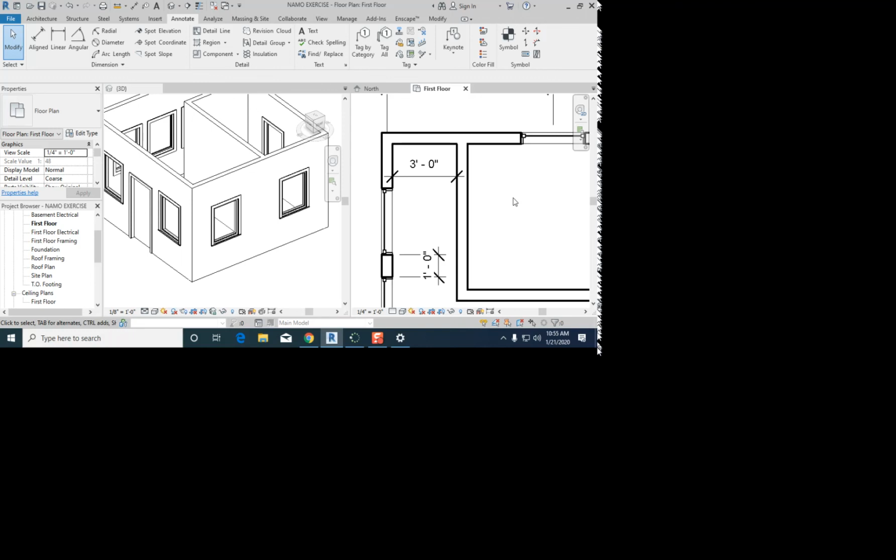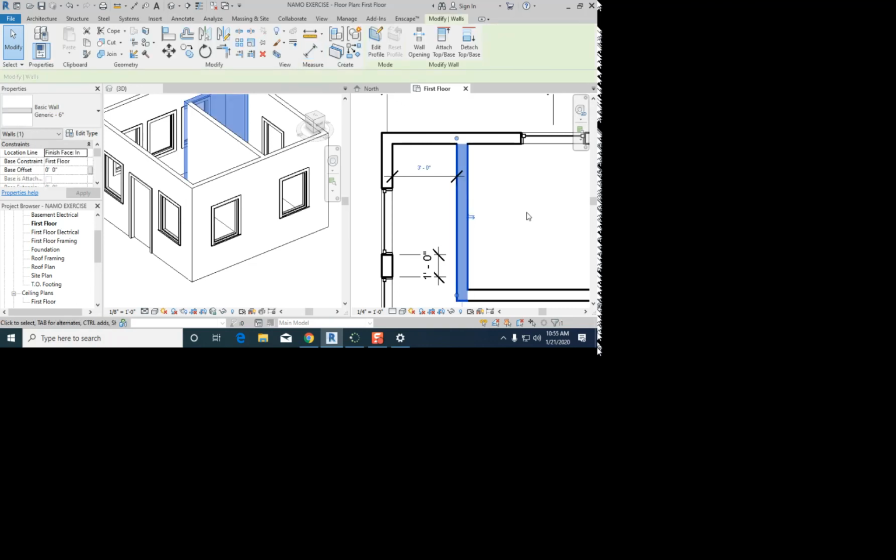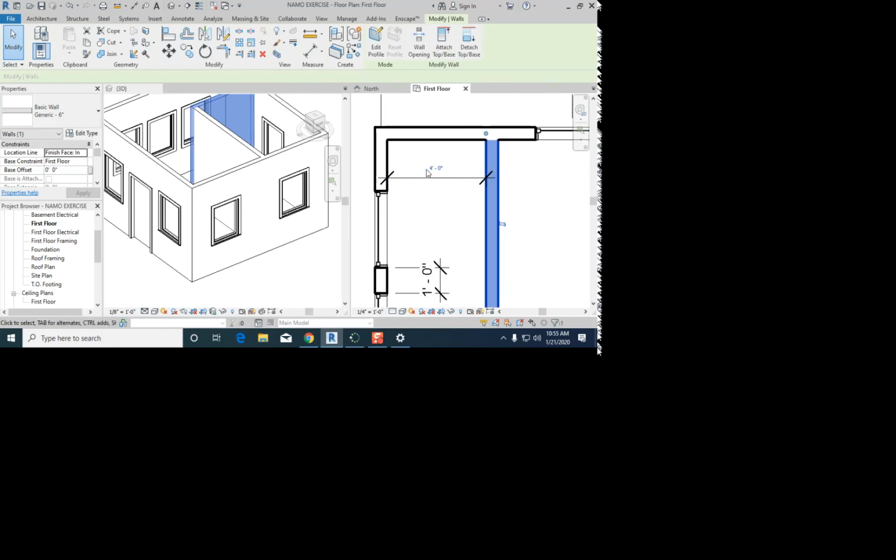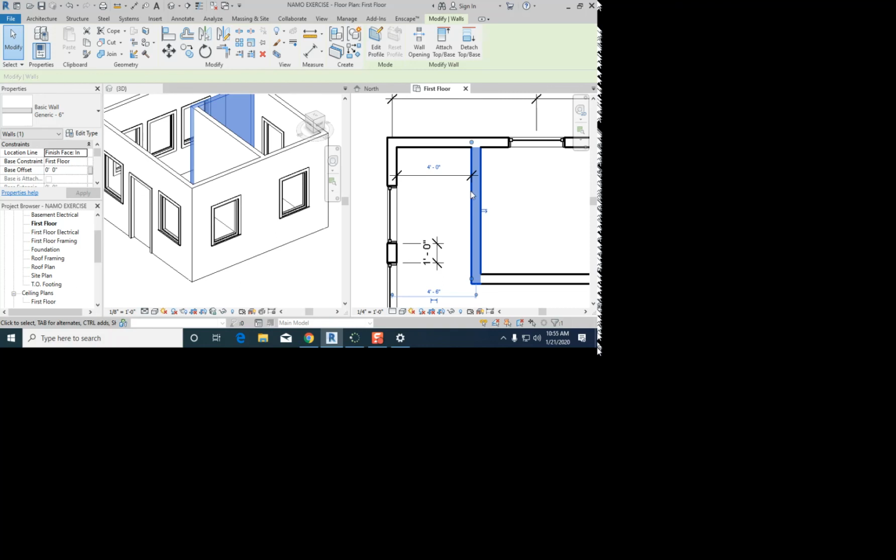So we are in the project site. If I want to move this wall, what do I need to click on? Click on the wall you want to move. This is the wall that we're moving. So my dimension gets highlighted and I type in 4, enter. Now we've got 4 feet from here to here. Do you guys want me to do that one more time? Yes? No? I don't see any furrowed brow.